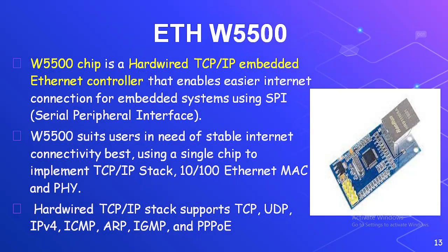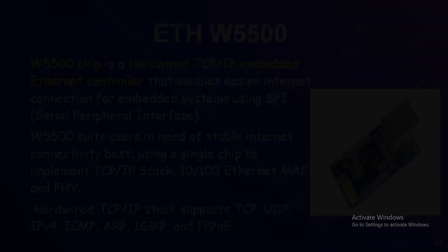Okay, and then Ethernet module. W5500 chip is a hardware TCP/IP embedded Ethernet controller that enables easier internet connection for embedded systems using SPI (Serial Peripheral Interface). It suits users in need of stable internet connectivity, using a single chip to implement a TCP/IP stack, 10/100 Ethernet MAC and PHY. Hardware TCP/IP stack supports TCP, UDP, IPv4, ICMP, ARP, IGMP, and PPPoE.